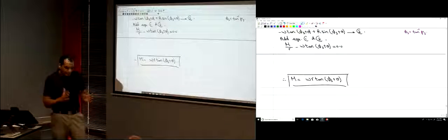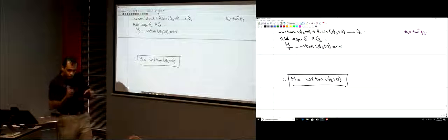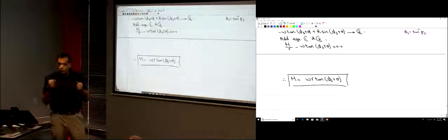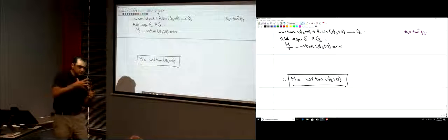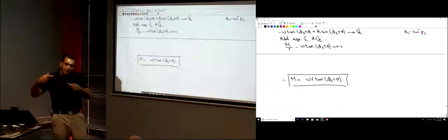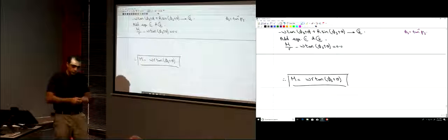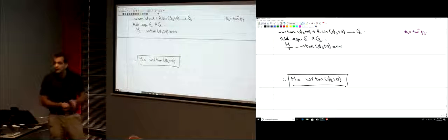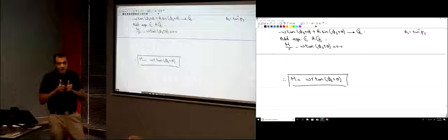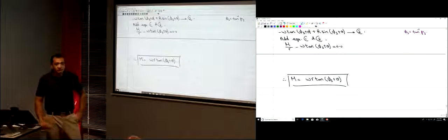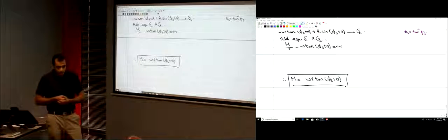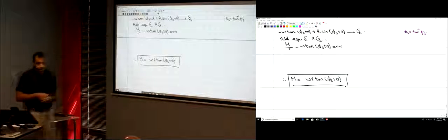When he tightened it so strong, he moved it to the limit, increasing this normal force W. It's not only the weight, he applied a vertical force on the screw. He moved it to the end, so the screw is under tension because he screwed it to the end. So he actually increased the force W. That's why now you need a larger moment to unscrew it.